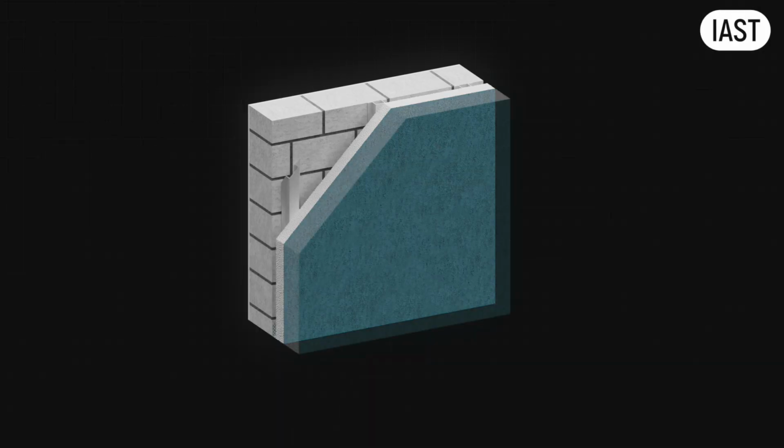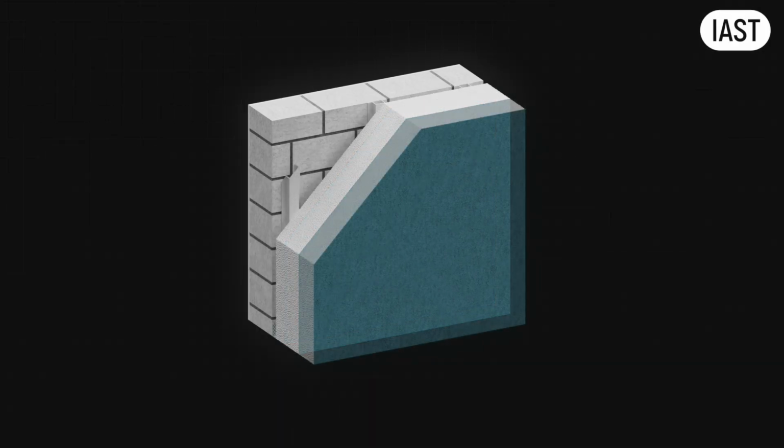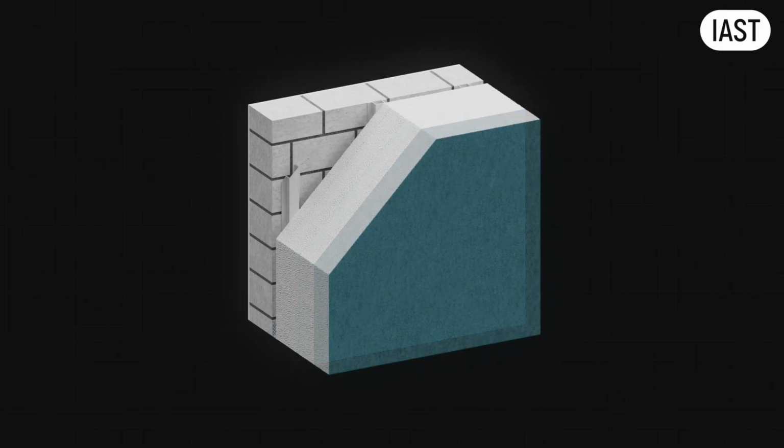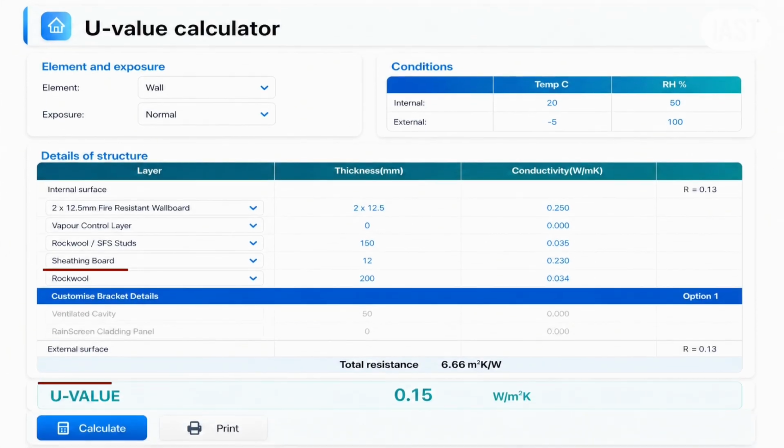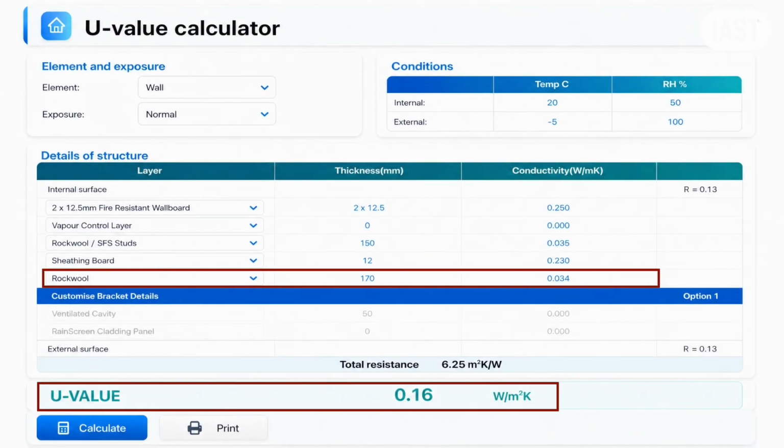Lever 1. Insulation thickness. At early design stage, this is the simplest move available. You are not yet locked into specification. Nothing has been priced. Nothing has been approved. You just lay in more depth from the start and the R value responds immediately. Once the project is further along, even this lever becomes complicated. So use it early while it's still free.